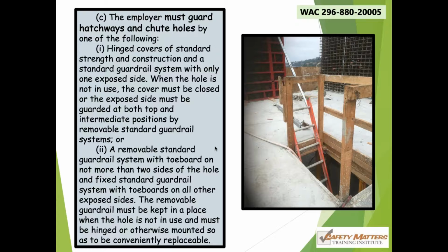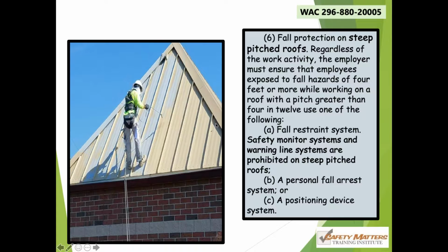We need to use a removable standard guardrail system. We should have toe boards around all open sides. We should have a rail system right here, so when I climb up that ladder, I remove the rail, I step off the ladder. If nobody's coming up behind me, I put that rail system right back on. I want to point out that this ladder does not extend the appropriate 36 inches.